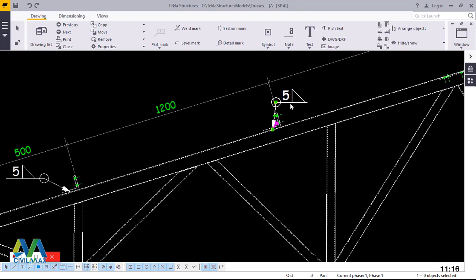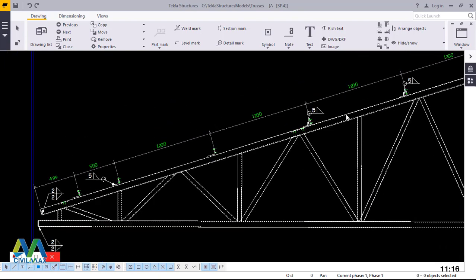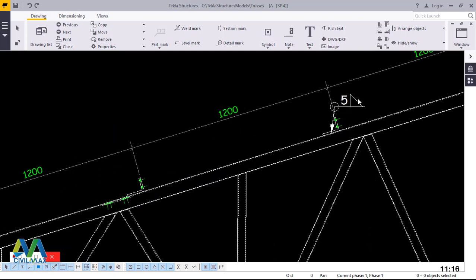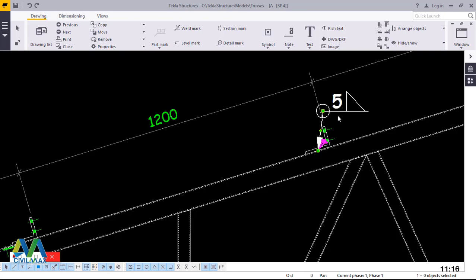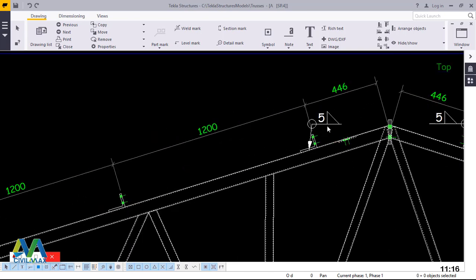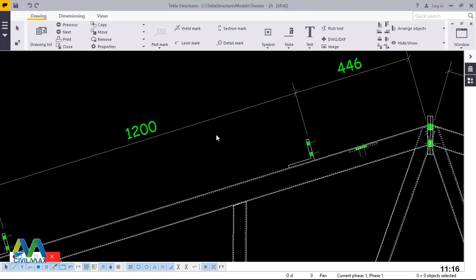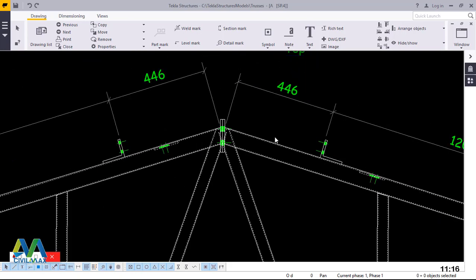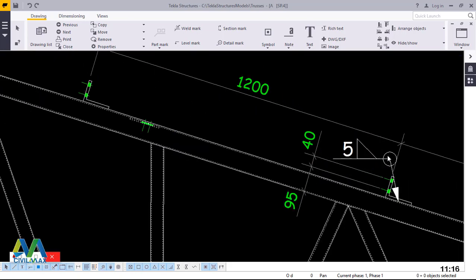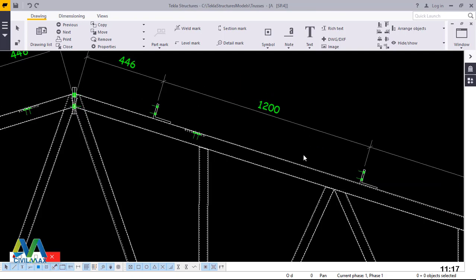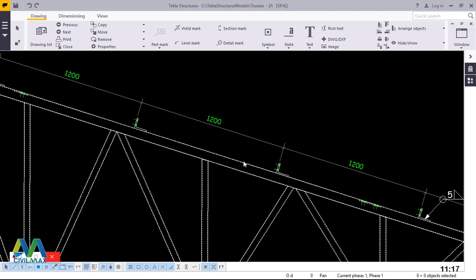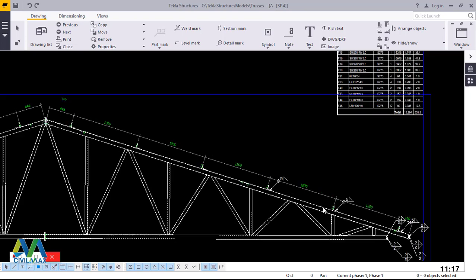Now I'll go ahead and delete this. I'll delete this one and come here and delete this, so that we have one, because it's typical weld for all cleats. I'll click that and delete, and come all the way here and click here and delete. And the other end also I'll delete that, so that we have only one typical weld, so that we just duplicate 2 other parts. Let me delete only the unwanted parts.